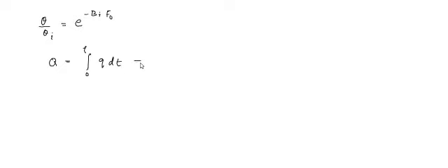And we have seen that this will be equal to hAs times the integral of 0 to t of theta dt. Now what is the value of this theta? This equation is obtained from the previous slides or previous video. So Q is equal to hAs times the integral of 0 to t of theta dt.